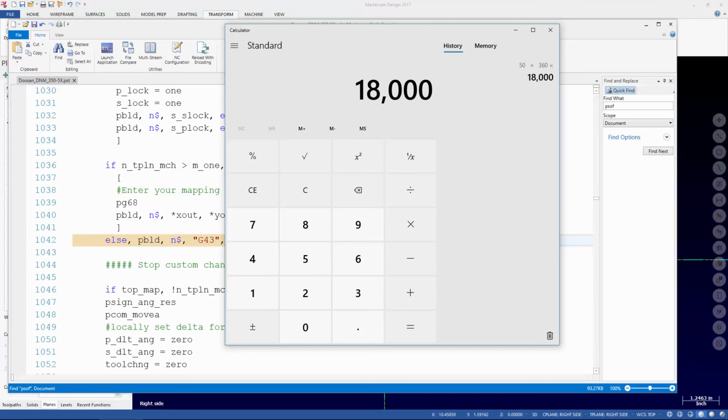Some do. Some will have what's actually called a turning mode, where you can just say, spin my C axis at 20 RPM. I think 20 RPM is actually your limit, or maybe it's 30. But spin my C axis at 3.258 RPM or something like that.